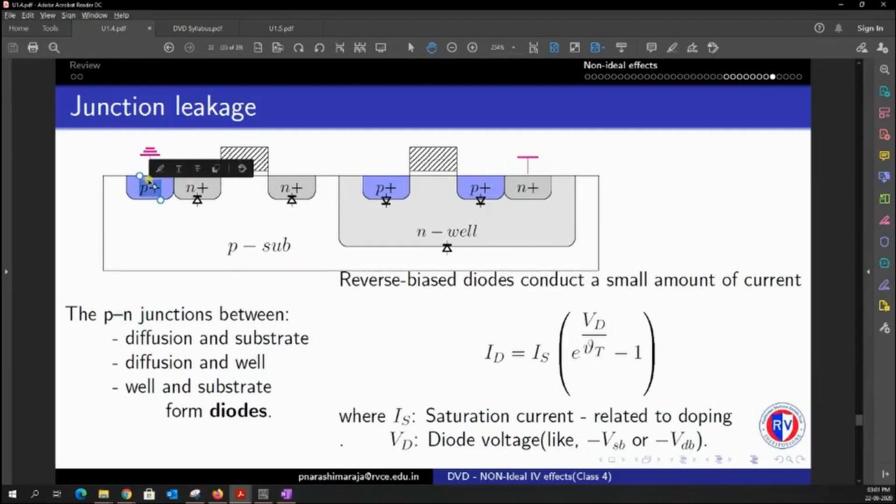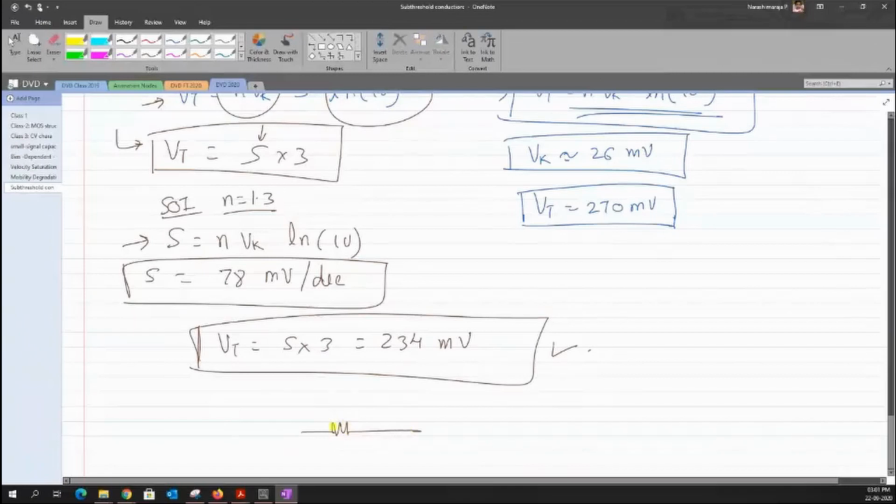reduce the resistivity, because even the resistance of the material will also matter when we try to apply some sort of potential. Say, for example, if I have a very large resistance, the voltage that I'm applying here, 5 volt, will be dropped very heavily when the resistance is large. Okay, so we want to reduce the resistance so that I could at least produce something like 4.9 volt if the value of resistance is small.